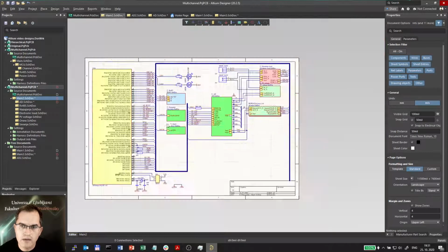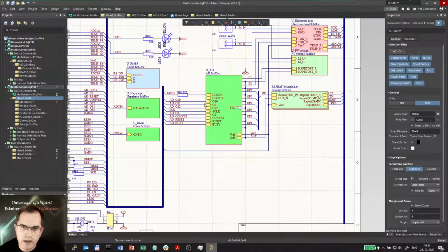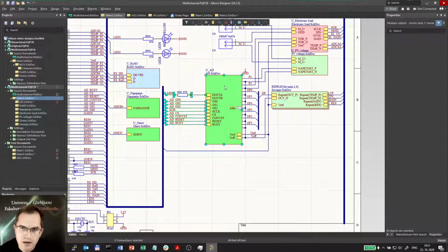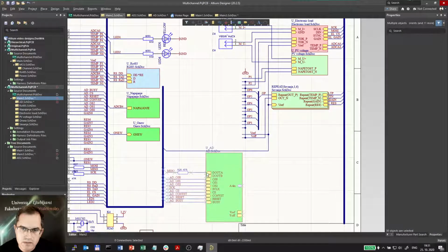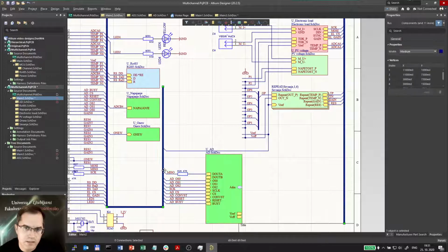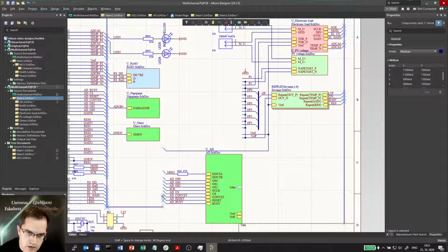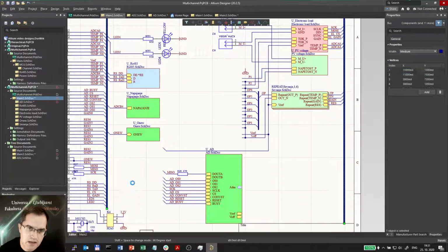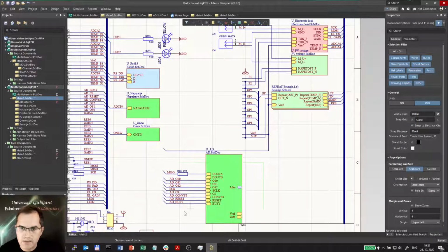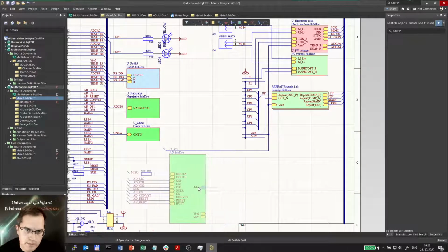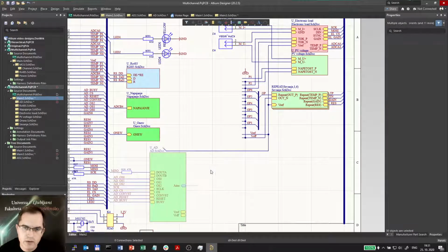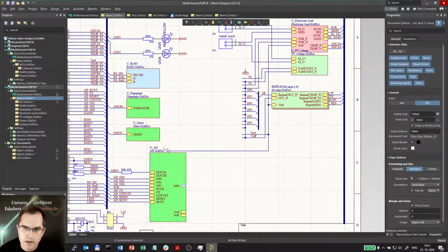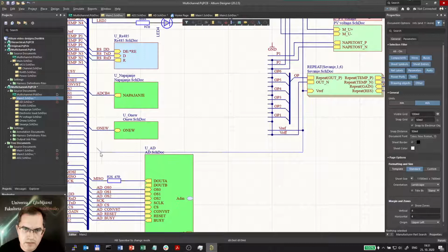And now I can move this block downwards, selecting everything except the bus, control, downwards. I can also delete the bus. Deleting the bus is quite awkward. You have to actually move it from the vertex to vertex until you finish here, because deleting it segment by segment is not possible. I don't know why. Maybe you have a solution. If you do, just post it below. Okay, this seems to be fine.